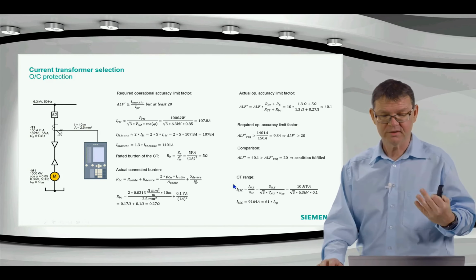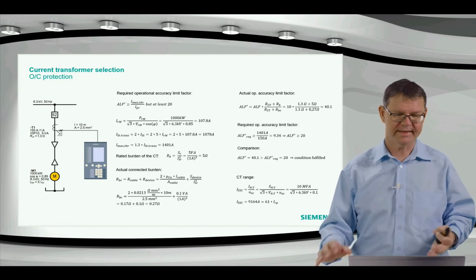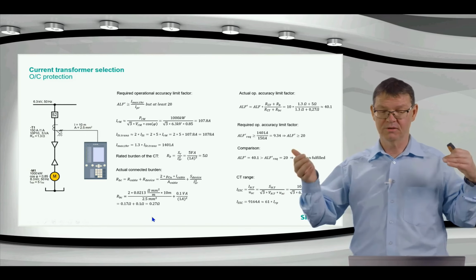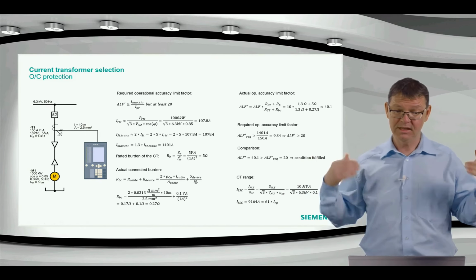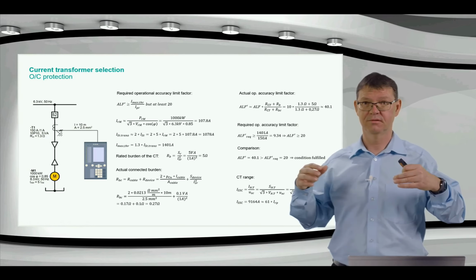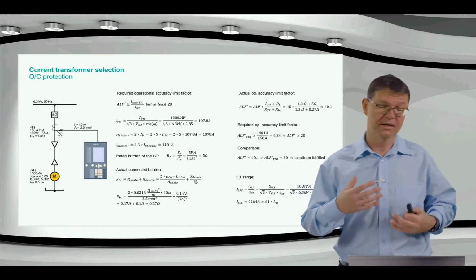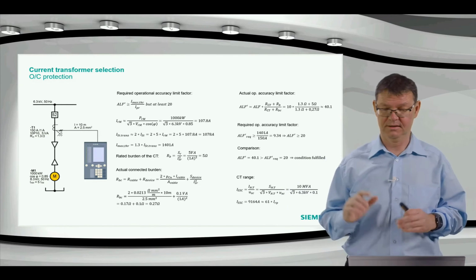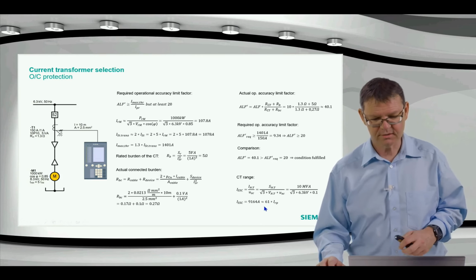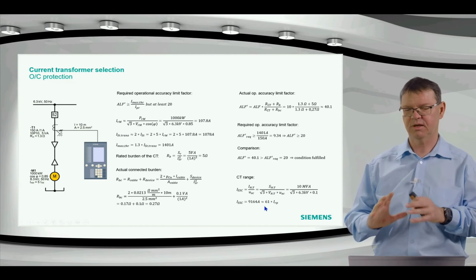Even for the differential protection, if I use identical current transformers on both sides here, then they will have the clipping equally on both inputs. So the differential current still is roughly 0. So this does not have an effect either for the differential protection. Just to mention that, to keep that aspect in mind, therefore I put it here.